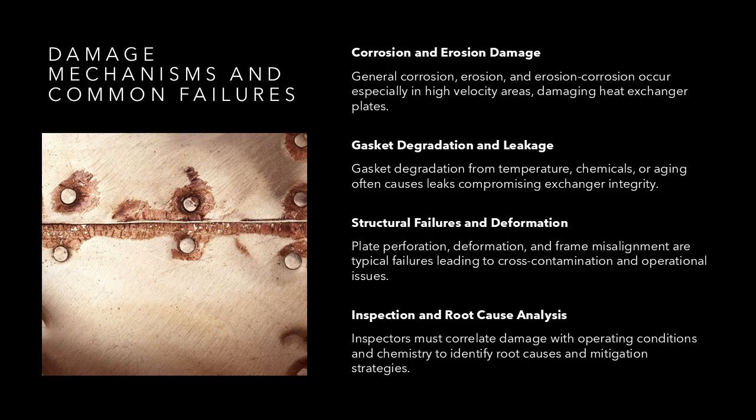Gasket degradation due to temperature, chemical exposure, or aging is a frequent cause of leakage. Typical failures include plate perforation leading to cross-contamination, repeated gasket leaks, plate deformation, and frame misalignment. Inspectors should correlate observed damage with operating conditions and process chemistry to determine root causes and appropriate mitigation.